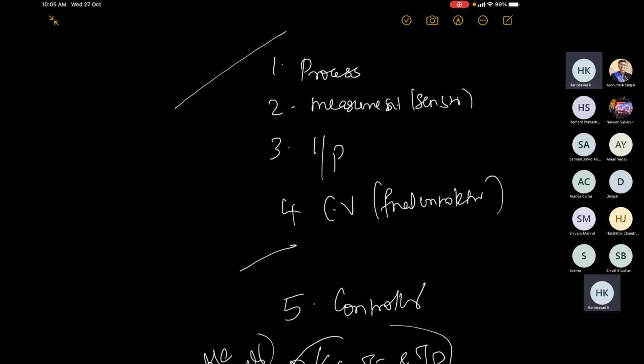Okay, so as a process control engineer or scientist or whatsoever, you tend to address the problem of controlling something. Let's say, if it is a distillation column, controlling the temperature of the tray, or a CSTR, the outlet concentration, and so on and so forth. You studied the process and got a good understanding of it. Then you started putting the instrumentation around it because you understood that you need to control the temperature, so you need a measurement.